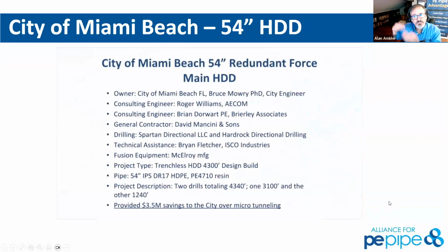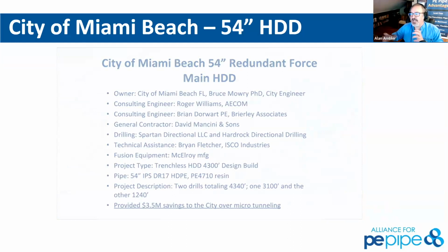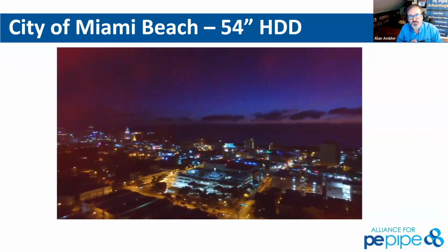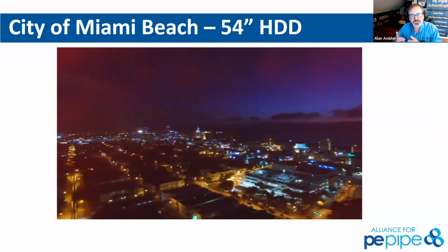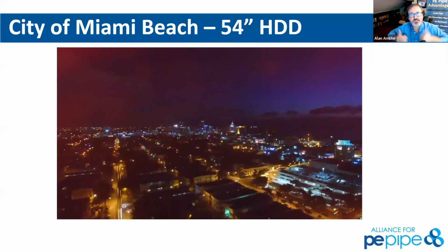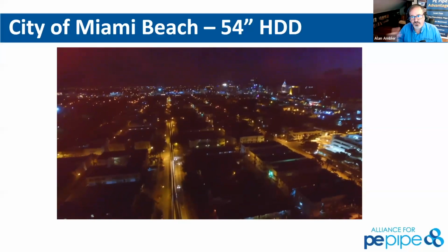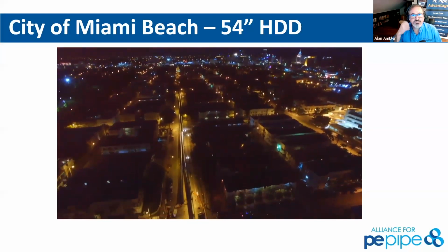We're continuing to push the boundaries. That pre-stressed concrete cylinder pipe slip lining, compression fit slip lining, is going to continue to grow. One of the major reasons why is resin development is pushing us into larger diameter pipes with higher and thicker walls as we continue to install and push those boundaries.